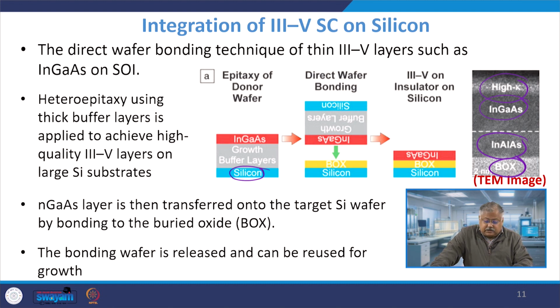The native oxides of III-V material easily result in what is known as Fermi level pinning, right? And thus the gate is unable to perform a very well defined current flow because the Fermi level pinning takes place, right? That is the reason why III-V MOSFETs have not made good progress for a long amount of time, because of the pinning, and you don't get enough free electrons available to you to participate in the current flow.